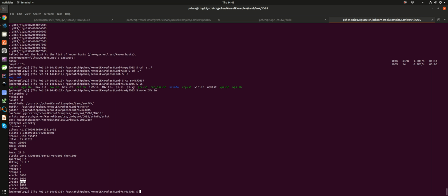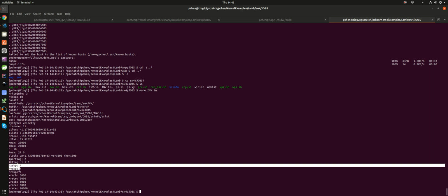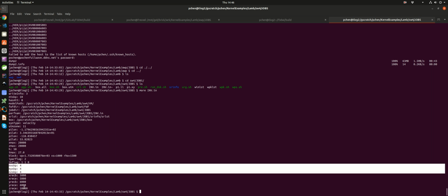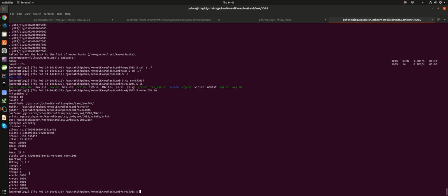and then stop saving at 6 kilometers before the end of the largest y, and then in the z direction I'm saving down to 10 kilometers depth. So this kind of range for saving the strain fields is a new capability. The spatial decimation rate is similar, and the time decimation rate here I'm specifying as 10, and this is actually quite large, so there will be some